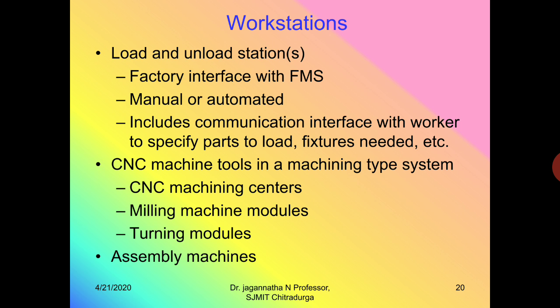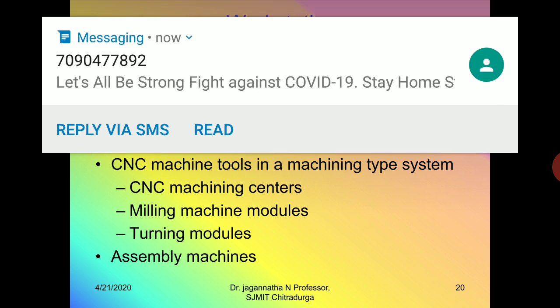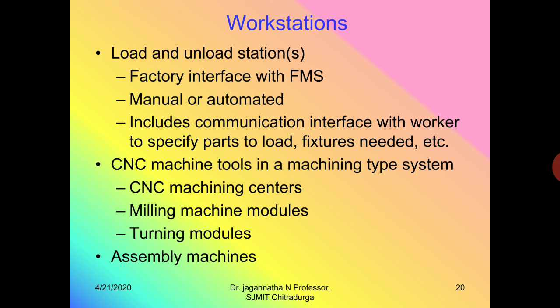Workstations. The function of workstations is to load and unload the station. That is the factory interface with the flexible manufacturing system. It may be manual or automated. CNC machine tools in machining types of systems can be used as vertical assembly machines.